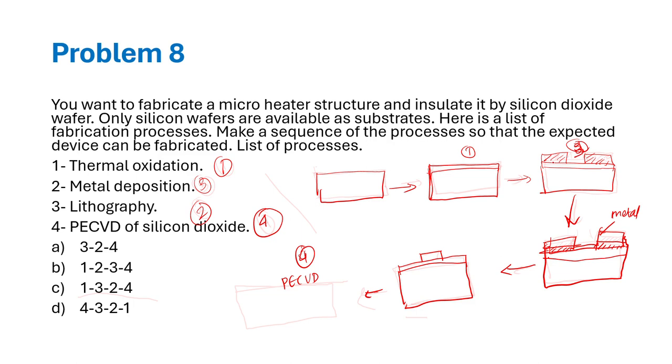So now we'll move on to the next question. Pilling-Bedworth ratio, silicon dioxide to silicon volume ratio, which we saw in the previous question, is given as 2.19. So what would be the thickness of oxide film that has formed if 10 nanometer thick silicon has been consumed during the oxidation?